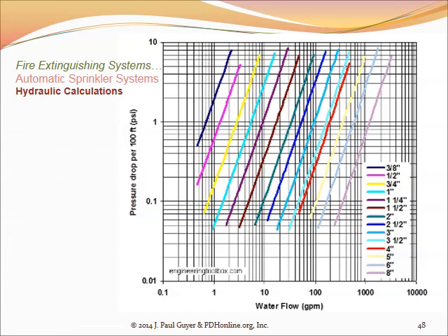So you might say that if you add it all up, you had come up with 3,000 equivalent linear feet. Well, since you can take a 30 psi pressure drop between the entry to the building and where the fire is, if you had 3,000 linear feet, that would work out to 1 psi per 100 feet of equivalent feet of straight pipe.